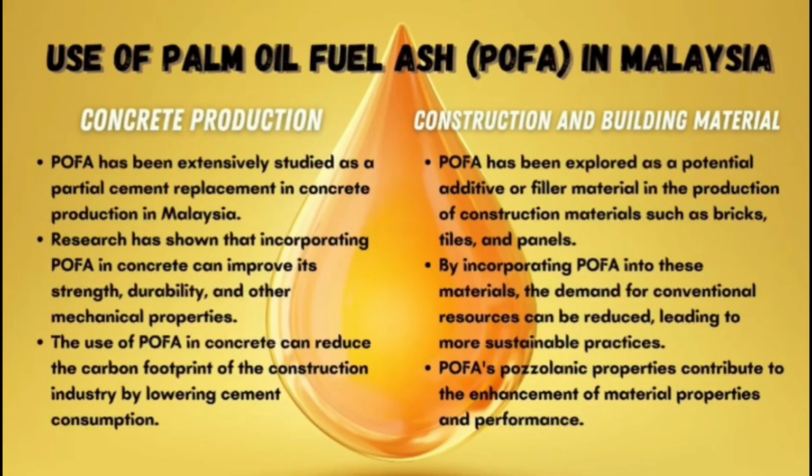Next, we move on to the use of palm oil fuel ash in Malaysia. For example, POFA can be used in concrete production. POFA has been extensively studied as a partial cement replacement in concrete production in Malaysia. Research has shown that incorporating POFA in concrete can improve strength, durability, and other mechanical properties. The use of POFA in concrete reduces the carbon footprint of the construction industry by lowering the cement consumption. So we can produce a better cement with POFA.